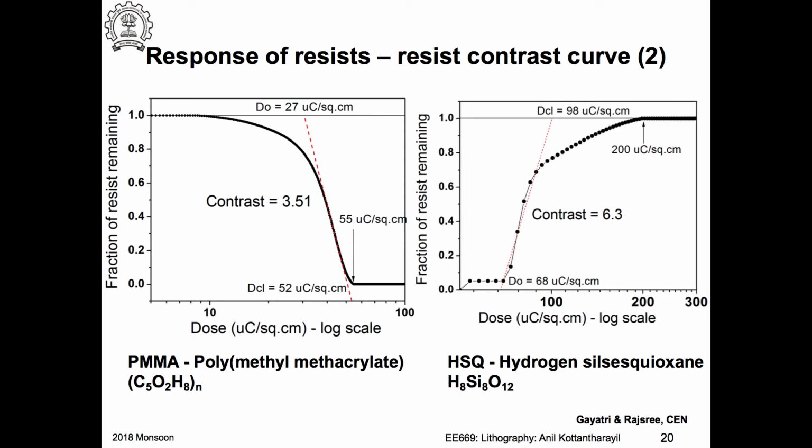You have the intensity of light that is going up, and then this is the image that is formed, right? And then the peak value is relative, okay, and that is normalized to the peak value, okay, and then it doesn't go to zero because of interference effects from two neighboring features. There is some residual dose.